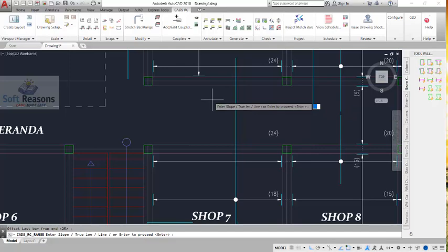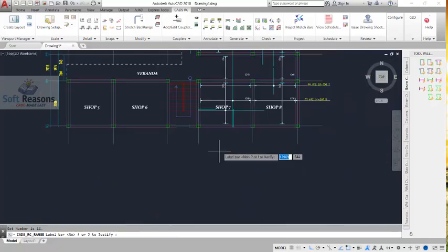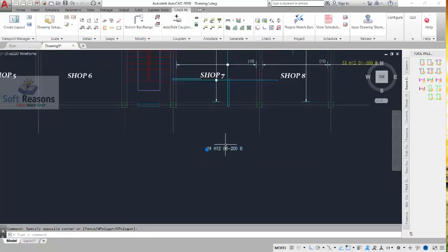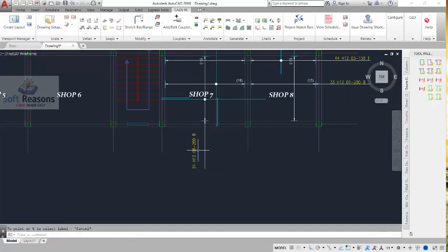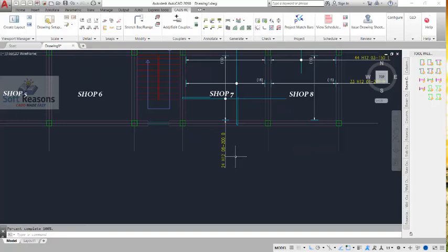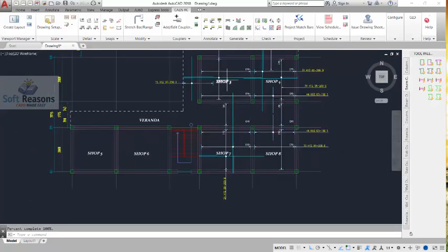Okay, 25. Enter again. So enter, and then you have now finished. Alright, so you have it placed just like this. You can place the bars here, rotate it, just like this, and then with that marked, take it all the way to this point, and then you can now move this here just like this. Okay, now we have detailed this provision successfully.